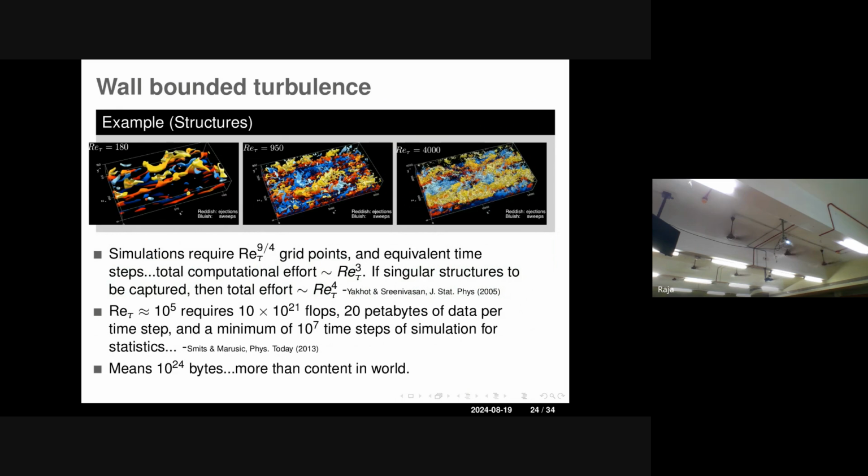What is meant by singular structures? Obviously, that is singular here. They always show some intermittency in the system, and that is what people usually connect with singular structures. Is it a spatial singularity? You can say these are spatio-temporal structures acting at very small scale, not like the high-speed or low-speed streaks. But I mean, it is singular in what? Is it singular in velocity gradients? You will have huge velocity gradients. That means you will have huge turbulence stresses also created.